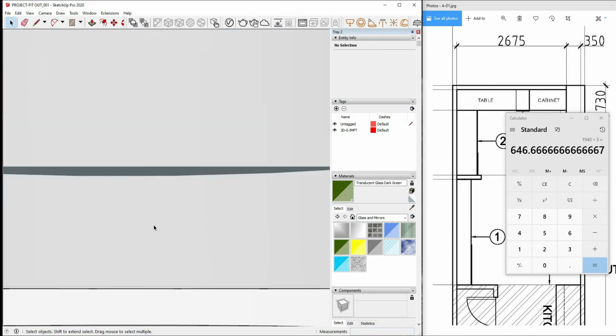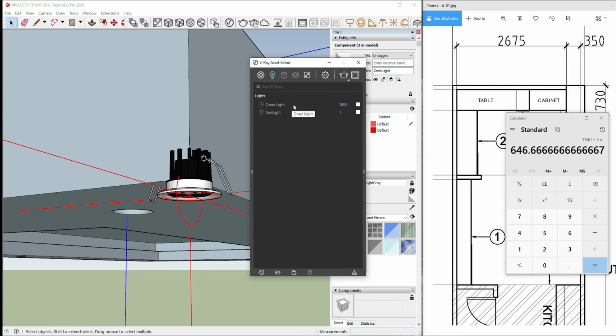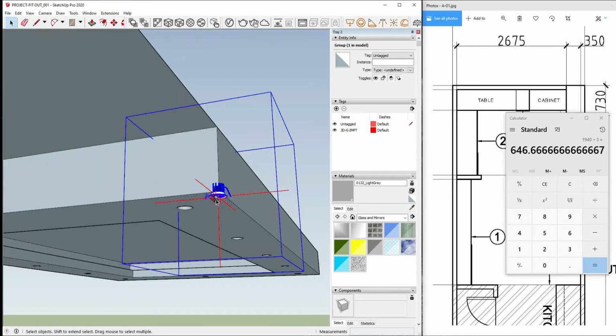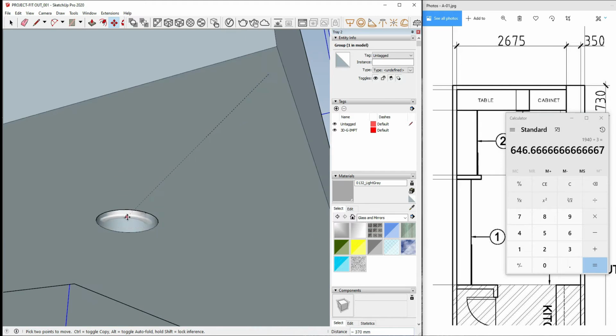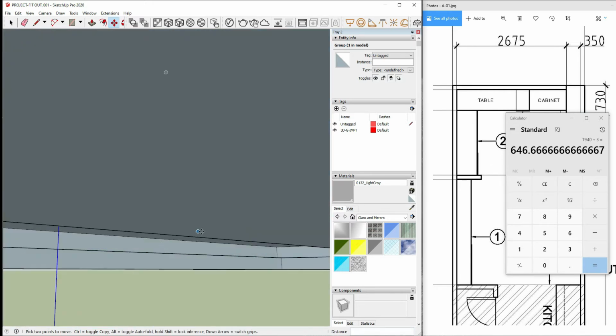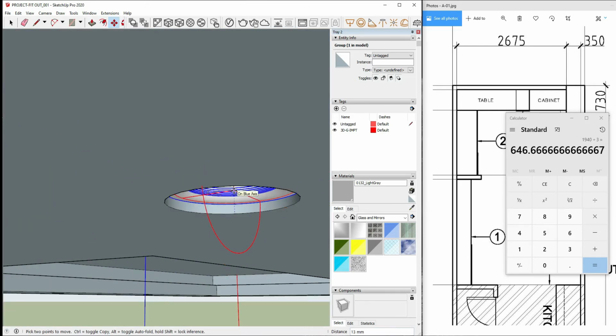Here, I bring the pen light fixture to the false ceiling. Carefully, we will add the Omni light from the V-Ray panel tab to this pen light fixture. As you will observe, I create a group to make this one object, because we only need one type of light for the same type of lighting fixture. In this case, we can easily modify the intensity and specification of the light when we render it with V-Ray.